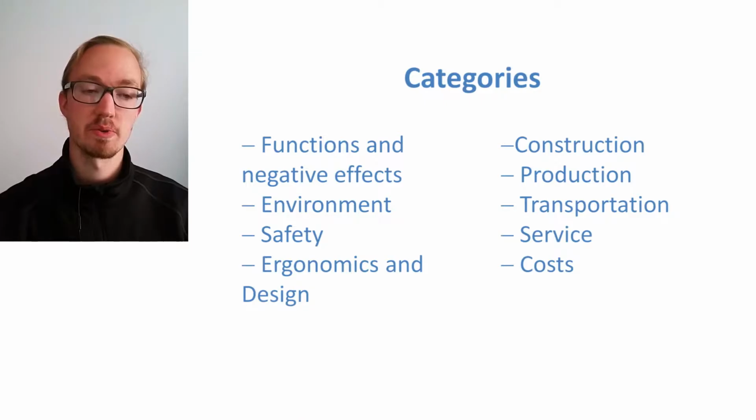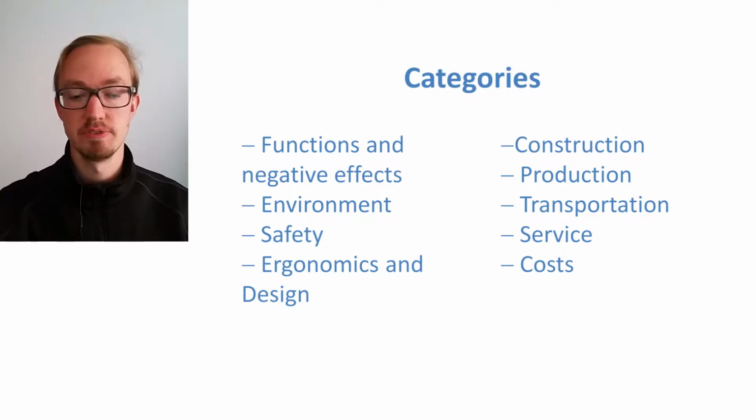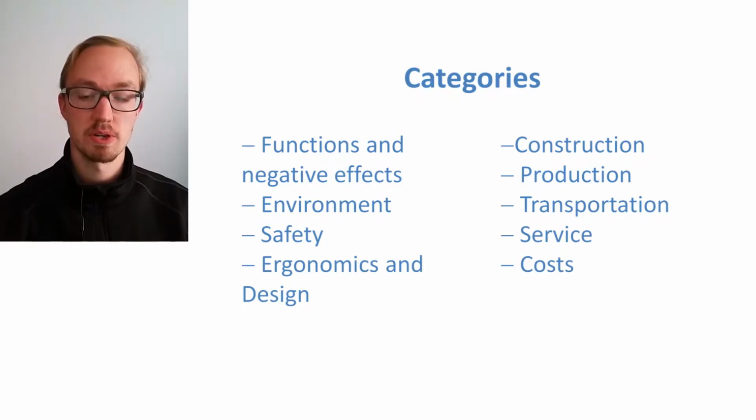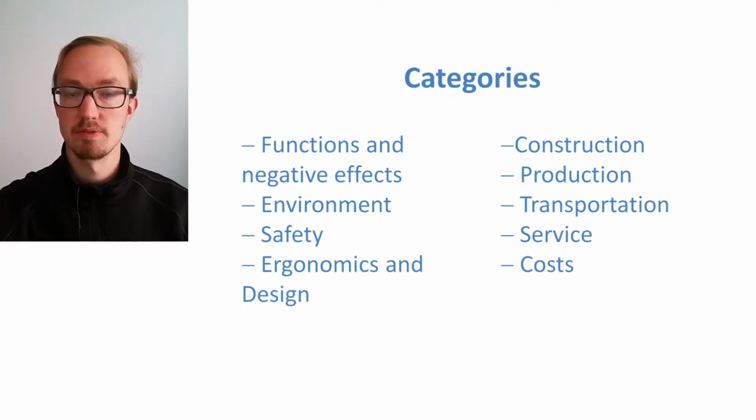Construction is everything regarding physiology of the device, what material you will choose, where the location of parts is, and, for example, a criteria like maximum weight, adaptability or individuality, passive cooling, symmetry, all this. Production could be the manufacturing process or the details about production questions. You could say that, for example, the product has to be 3D printed or it has to be welded. This could be all required depending on, for example, the costs that you have.